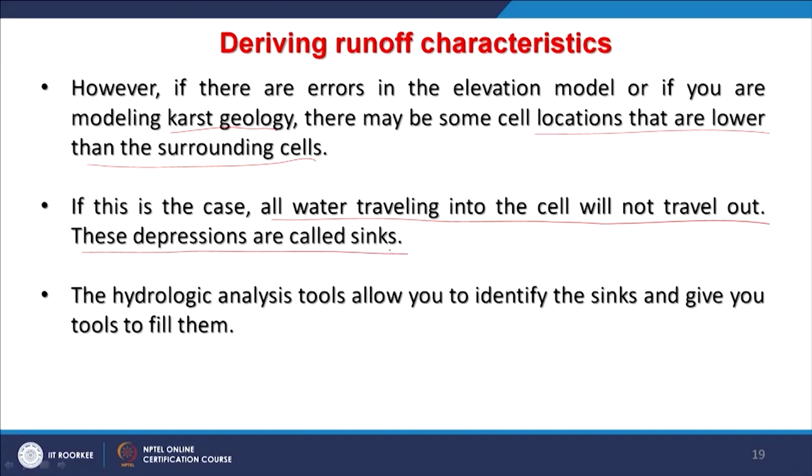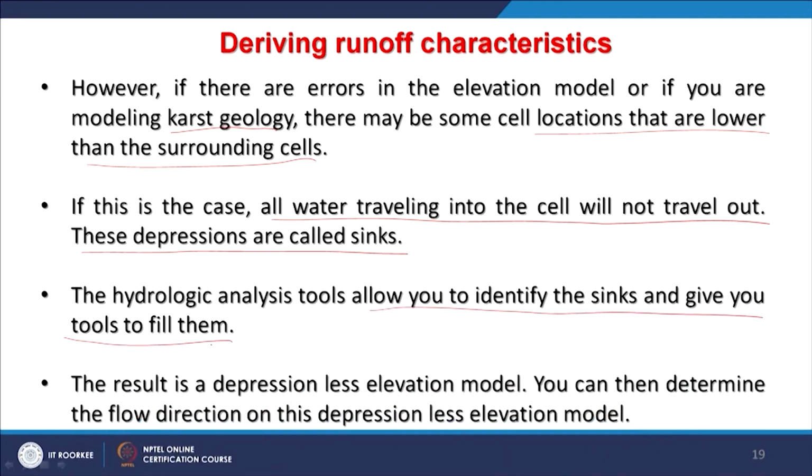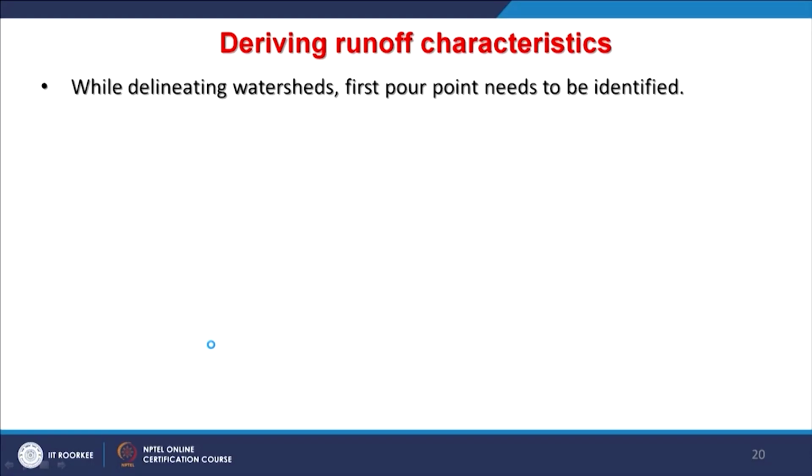So, the surface hydrologic modeling tools which are available in most of the popular GIS software will allow you to identify sinks and give you tools to fill them. I have shown the example also. And ultimately then you will have a depressionless elevation for further processing.